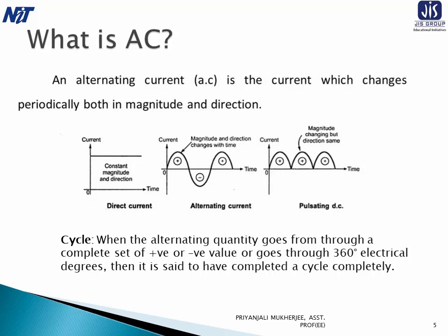Now in our country, the standard voltage for low tension distribution is 240 or 415 volt. That means 240 volt between phase and neutral wires and 415 volt from line to line. And this is a reasonably safe voltage. The higher the voltage used, the lower is the installation cost. That means economy is achieved, but an increase of voltage means more hazard to human life and property.